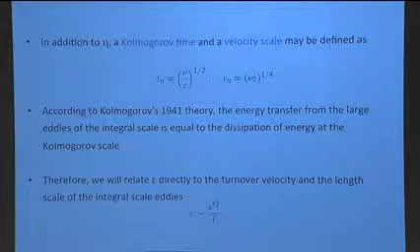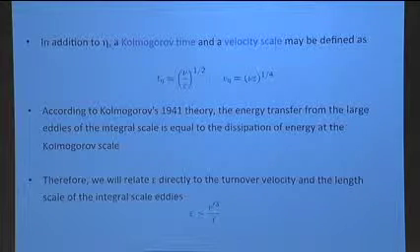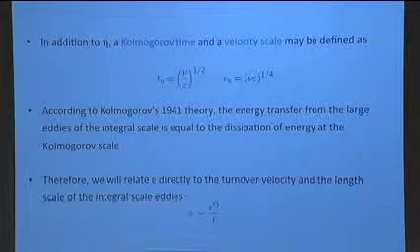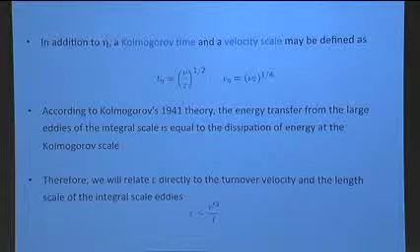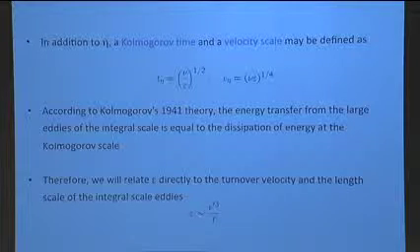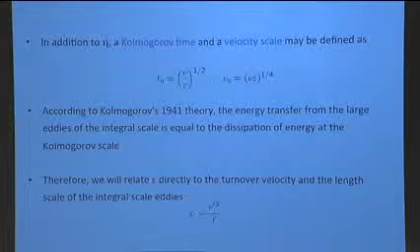And that actually is the same. It's just a consequence of what I said about number 2. The Kolmogorov scaling essentially tells you that, again, in the inertial subrange, the turbulence statistics, so the kinetic energy, depend only on the wave number and the dissipation rate. Which means that the dissipation rate, that energy transfer rate, is the same at all wave numbers.